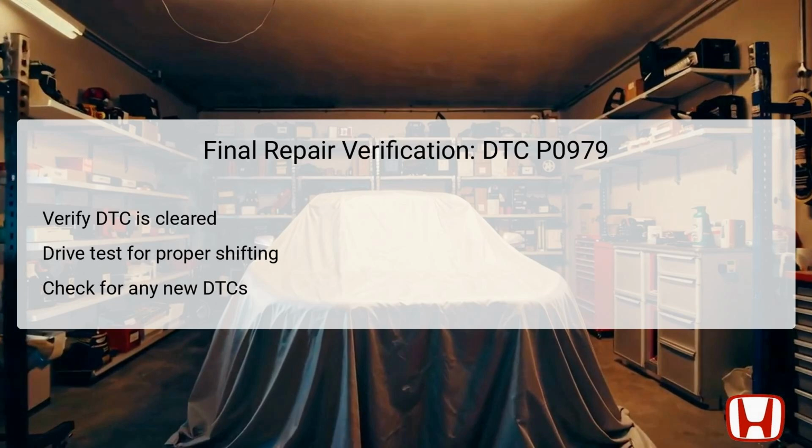indication of issues. During this test, be on the lookout for any strange noises, irregular shifts, or other abnormal behavior from the transmission. After the drive test, recheck the system for any new diagnostic trouble codes that may have appeared. This verification process is critical to confirm that the issue has been fully resolved and that the vehicle is operating